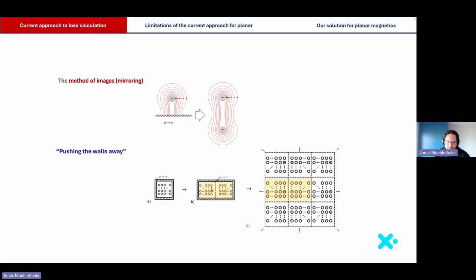You have the winding window, and you have now the conductors plus the conductors due to the air gap. Now you do this mirroring, which is a kind of an infinite amount of mirroring. We stop after some iteration, but what you end up with is a big plane with lots of conductors. And we are interested in the center window. That's where the actual window is.